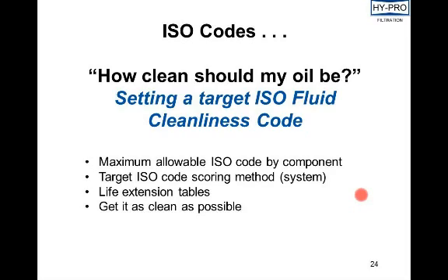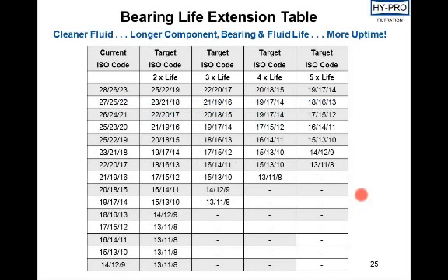The other approach is get it as clean as possible, and I say there within reason. You don't want to be changing filters every 2 hours and get that fluid so super clean, but you're consuming elements at a high rate and you're way below what your target would be. Get as clean as possible within reason and make it cost effective.